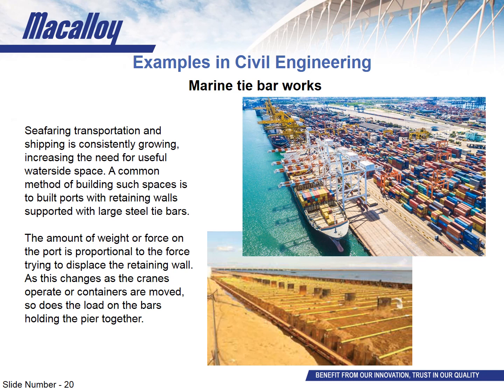ensuring fatigue demands are minimised is best practice for a sound structure. In marine tie bar applications, there is not often significant preload, so ensuring the absence of bending moments is priority. The use of articulation joints in the body of the bar and spherical nuts and washers at the ends gives the bars the greatest capacity and minimises fatigue demands.